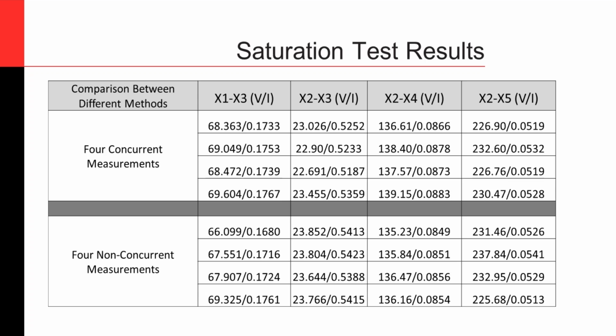We can do algorithms to look at the knee point and say if it is anything beyond a certain 5 to 10% of the value, it's a fail. But again, even a 750 volts response from the CT is not a bad value. It just depends on how you did the test and what results you got from the test.